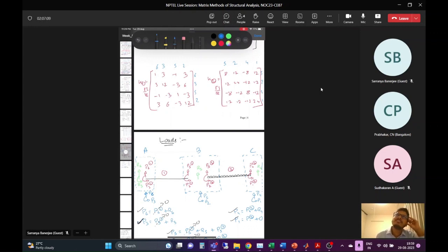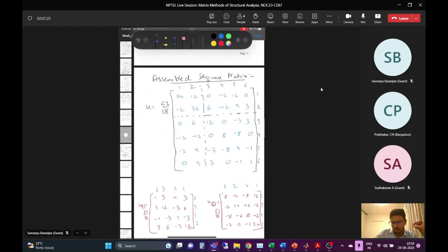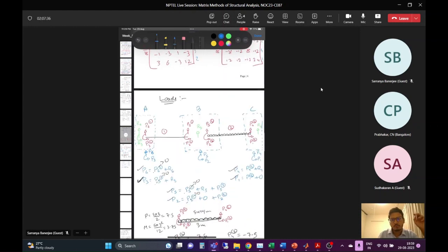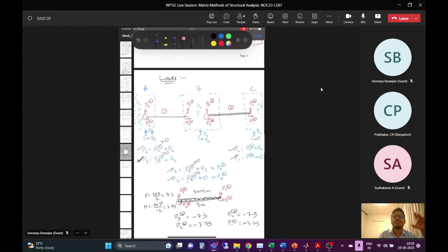Also, I think this is part of the definition of the beam, the features of the beam, like the boundary conditions. When we are doing the global stiffness matrix and making all the displacements at these last four joints zero, to make it consistent with the boundary conditions, we should also take the effect of the reactions into account, don't you think?